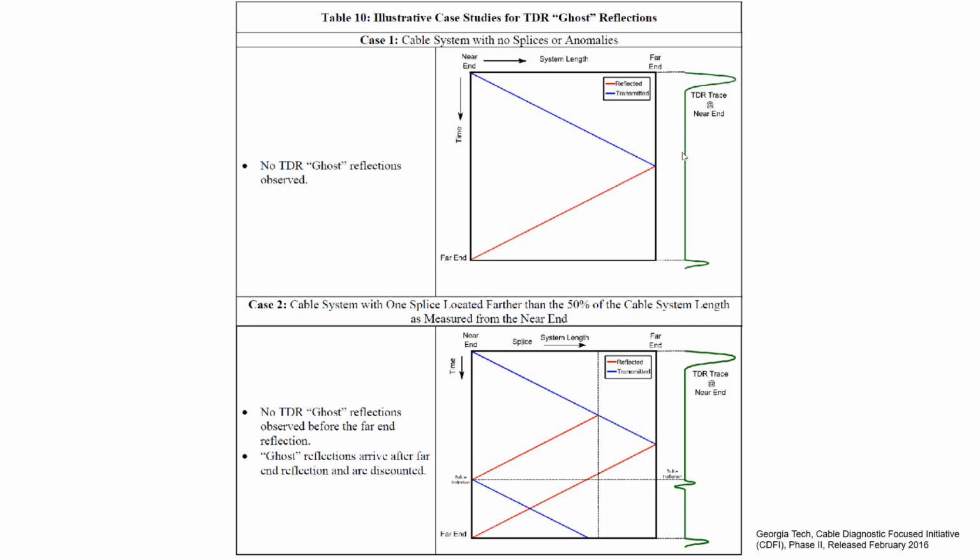This is the kind of signal you observe on the oscilloscope. Then there are no joints at all. There are no joints here. That's why this area is entirely smooth. There are no reflections. There are what is known as ghost reflections. There are no ghost reflections observed here. The reflections which occur, which are not true actually, which occur due to repeated reflections, are called ghost reflections. I will show you in the next